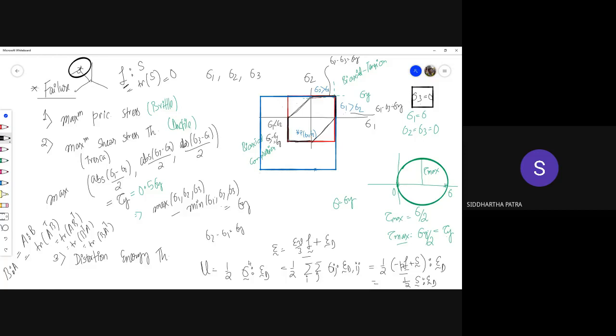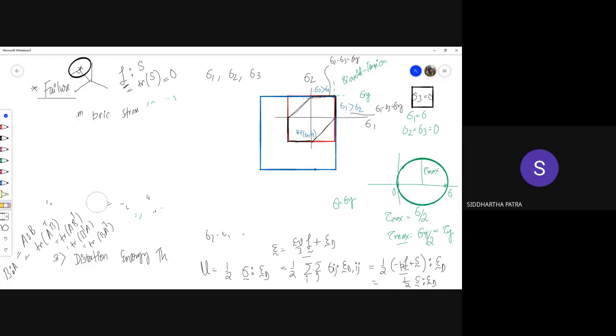Okay, so if I proceed further and go with the Lame representation of the stress, where stress is represented as lambda times trace of epsilon times I plus twice mu epsilon. And then what we did was we showed that it is lambda plus twice mu by 3 times trace of epsilon times I, where this is the volumetric strain, this is the bulk modulus, this is the regular shear modulus, and then the deviatoric strain. So then we said that this is minus p times I and s.